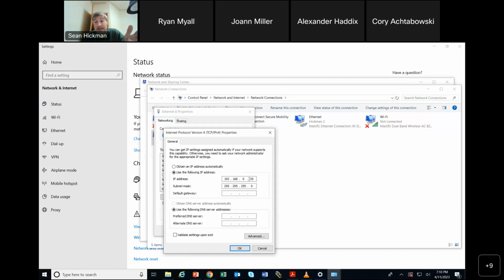When you get a piece of Allen Bradley equipment, there's another piece of software that's kind of doing what I'm doing here. It's called BootP, or RSLinx is a way to do it, or Connected Components is a way to do it. It depends on what piece of hardware you've got, what software you're going to use, and what it's going to look like. But you're basically doing what I'm doing here. You're giving something a static IP address. This is just the way you do it on a computer.